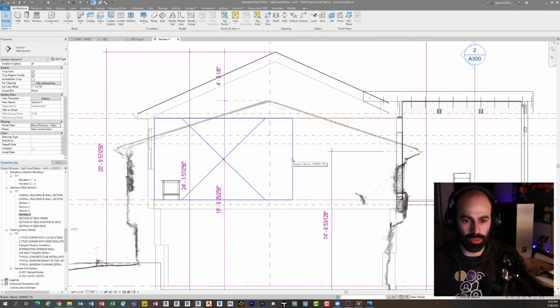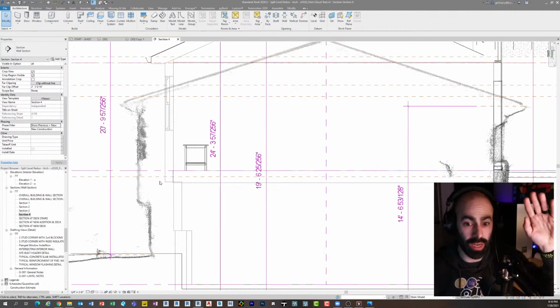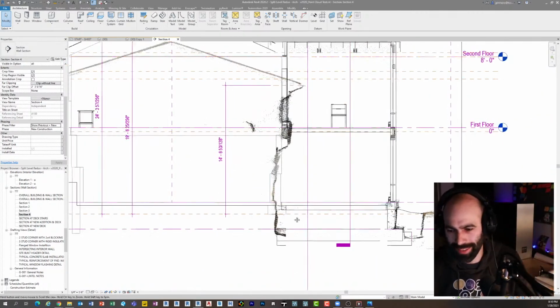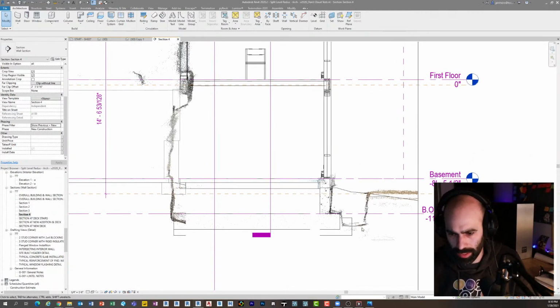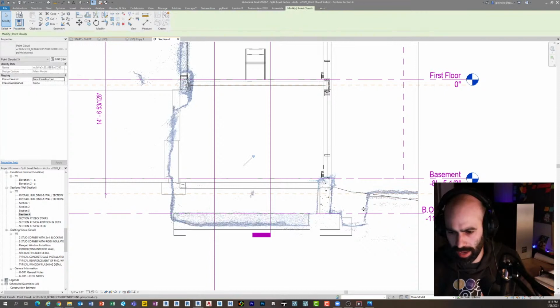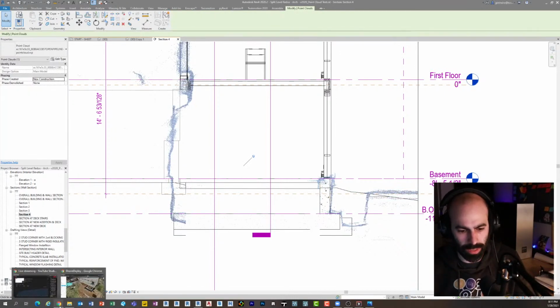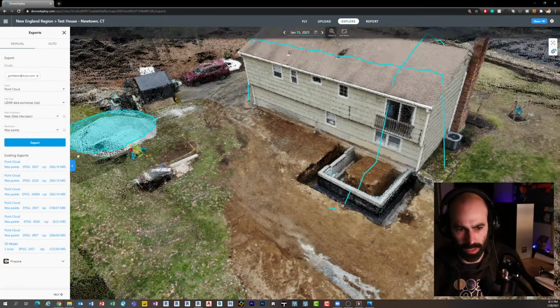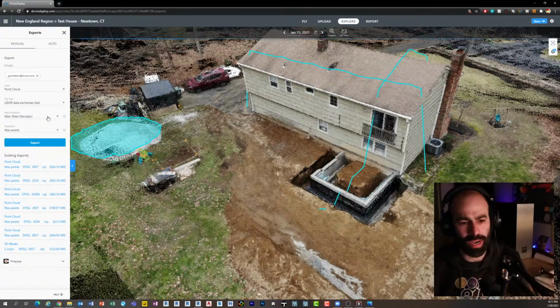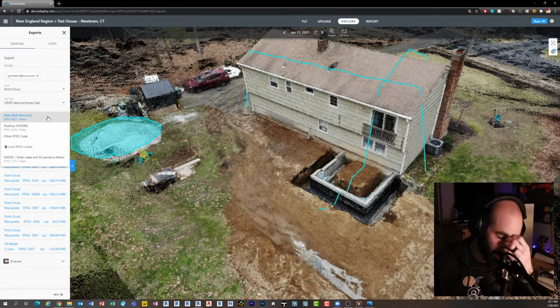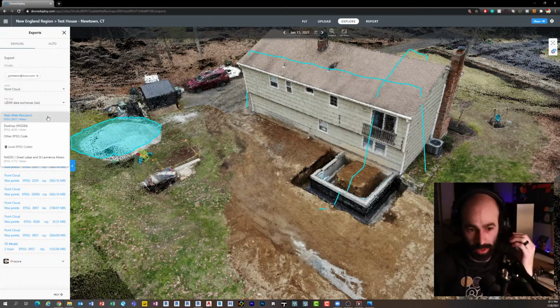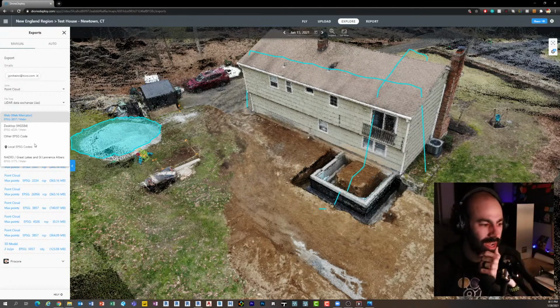This is actually a section through the point cloud, which, by the way, in and of itself is freaking wild that I could do this. And you can see even here, I go to wireframe. Here's the point cloud right there. And so I'm sitting there trying to figure this out, and thankfully the DroneDeploy people were very nice with support. And for anyone who tries to do this, there are these things called map projections, and I don't know if every software that creates these photogrammetries and these maps uses it, but these make a big difference on how you bring out your point clouds.